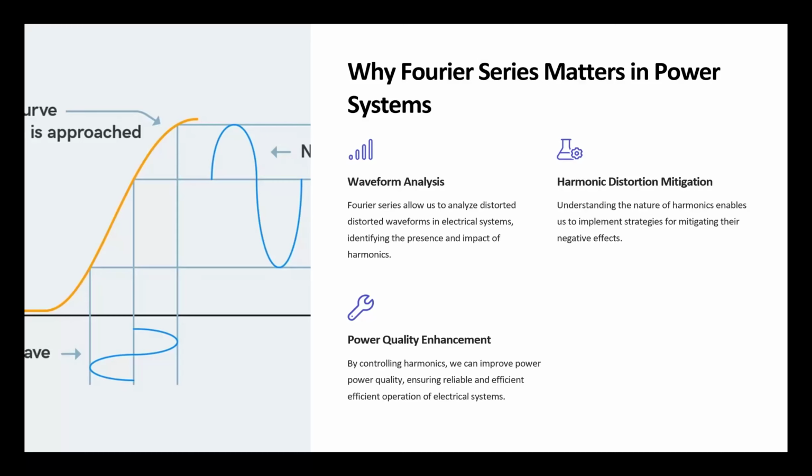Now we have two results for two analyses, one for 60 hertz, one for 180. Superposition gives us the opportunity to have the overall effect of the two by adding the two results of the two different analyses together. Now, you have a machine that works with 60 hertz, and a machine that works with 180. But the power of the 180 is lower because it's a harmonic.